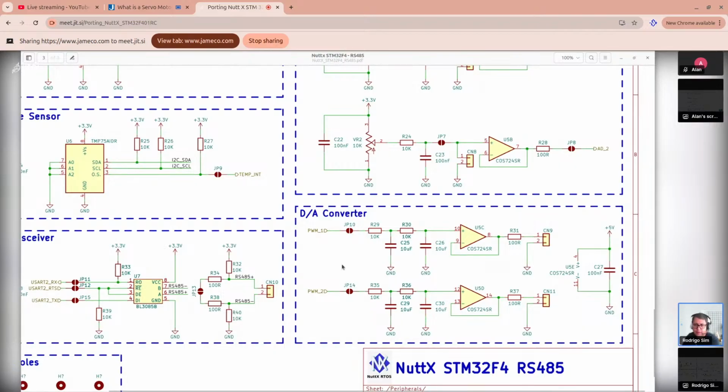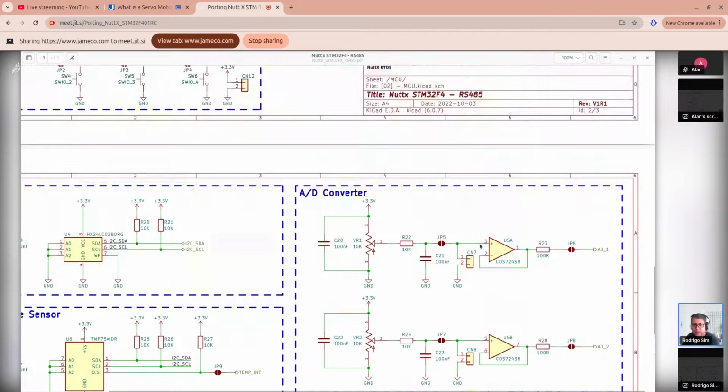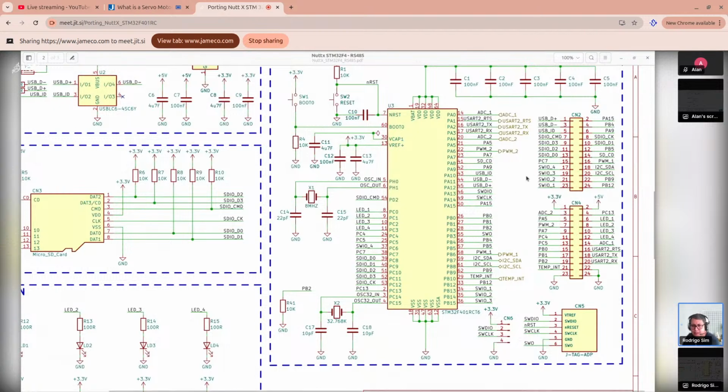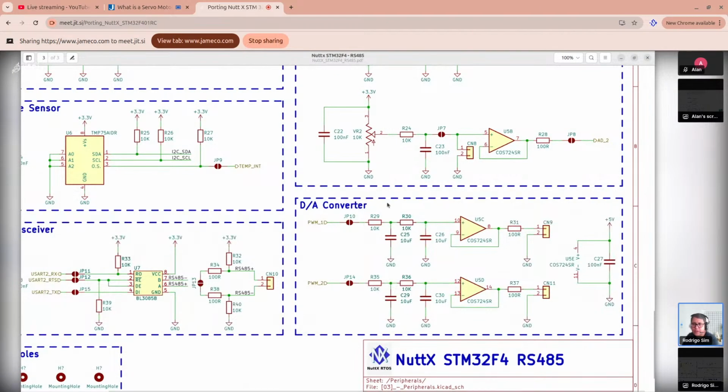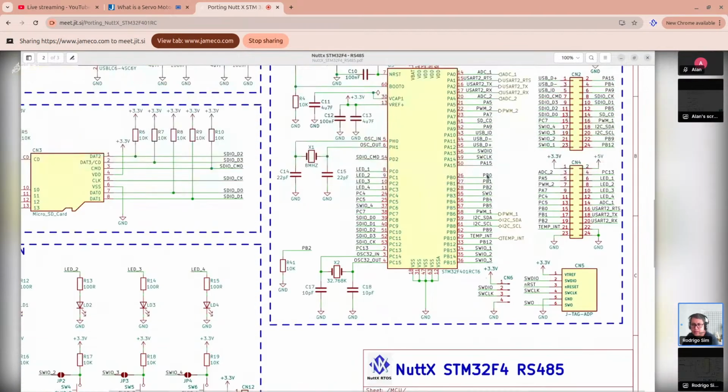So in fact, both of these are open and we could use PWM1 or 2, but I chose PWM2 here. This is open, and this same pin is exposed in your connector here, I think on pin 7. So that's what we're using to control the servo. The code will be the same, and I'm just showing the hardware, where we have opened this jumper so we can use the PWM here. Okay, so that's for the hardware.